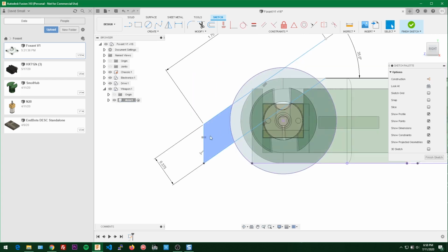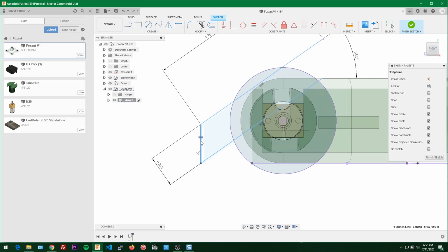So you may be tempted to define the position horizontally by selecting the circle and the line and then adding a dimension, but the problem with that is that the circle dimension is being defined by the center point. So if we were to define this and then make the circle bigger, it wouldn't scoot the arm over more like we need it to. So the way this should work is you should make the dimension,